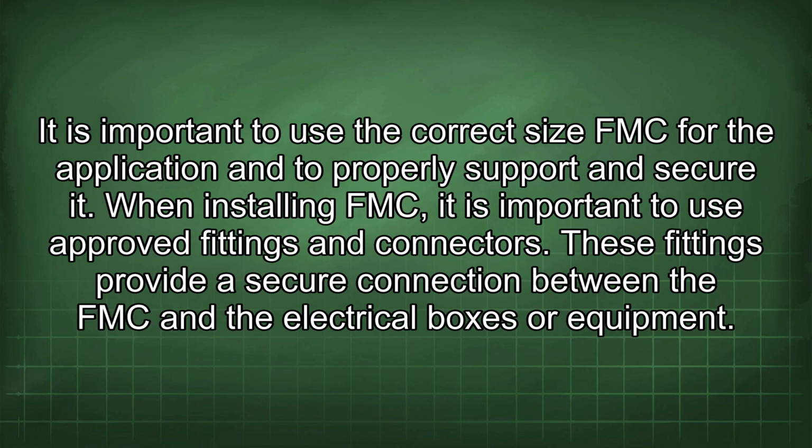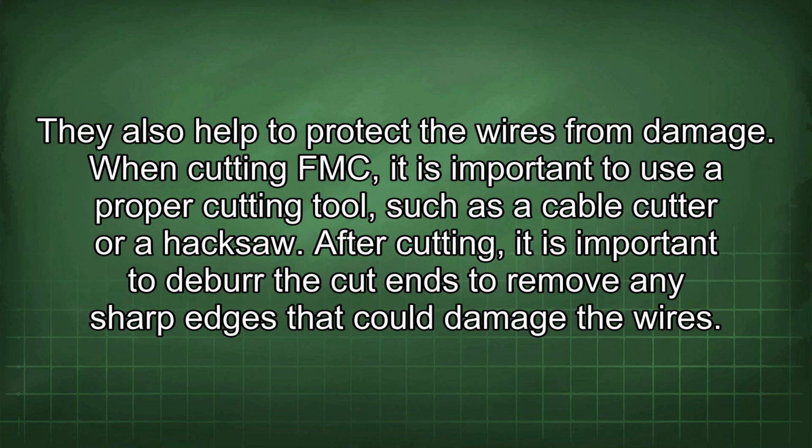It is important to use the correct size FMC for the application and to properly support and secure it. When installing FMC, it is important to use approved fittings and connectors. These fittings provide a secure connection between the FMC and the electrical boxes or equipment. They also help to protect the wires from damage.